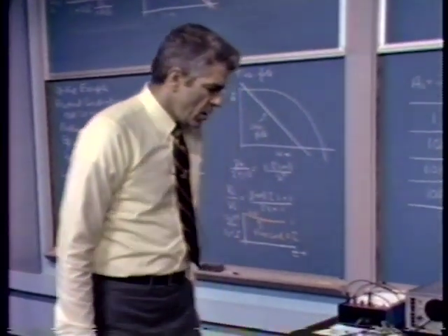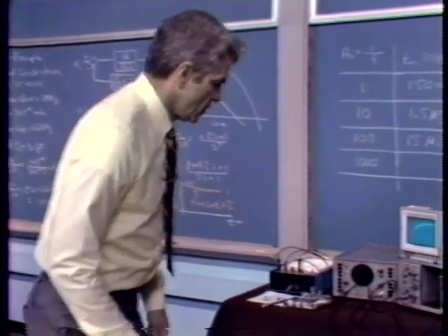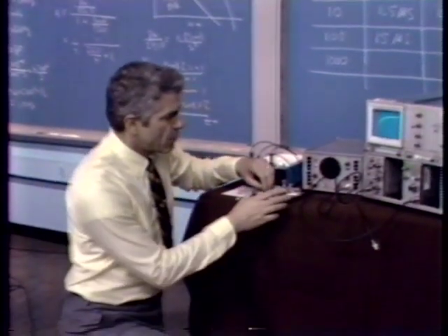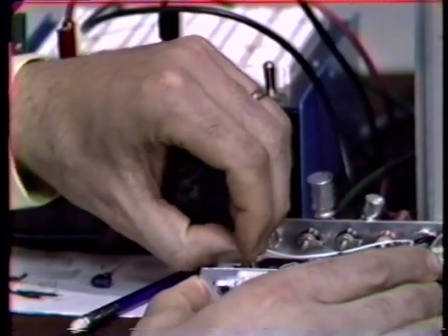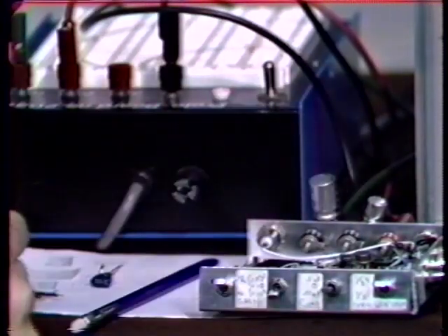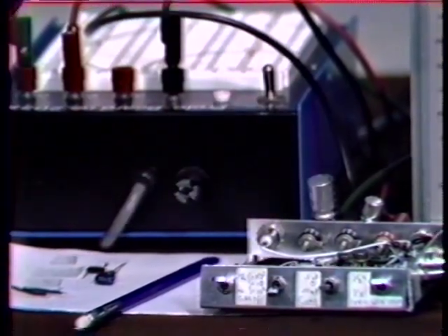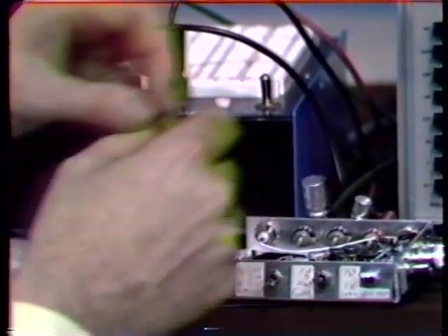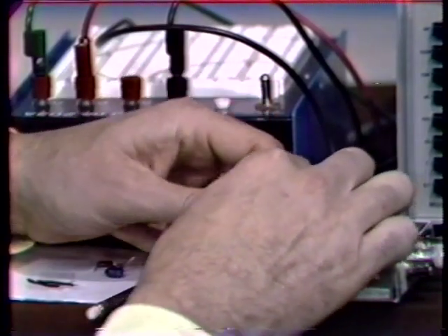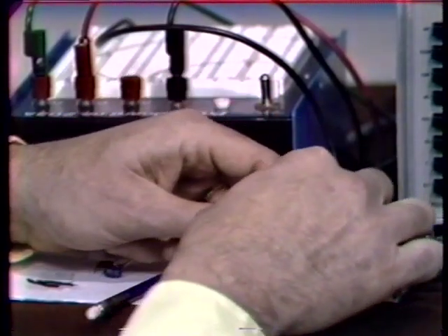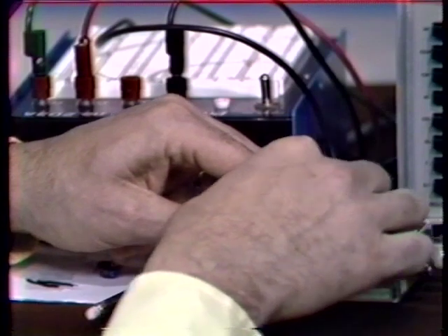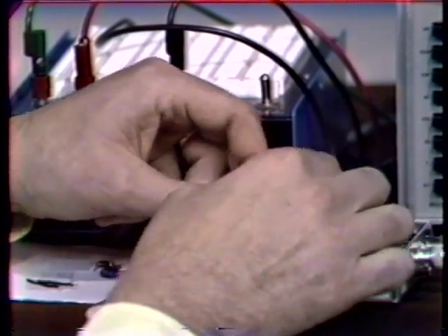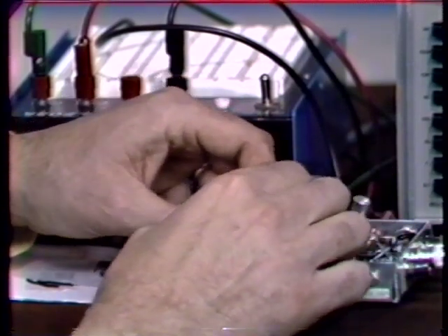Again, we can get close to our original speed of response by removing the 20 picofarad capacitor and replacing it with one that has been chosen. As I say, it's not quite 1/100th of the original value, but one that's been chosen to yield very close to the original dynamics.